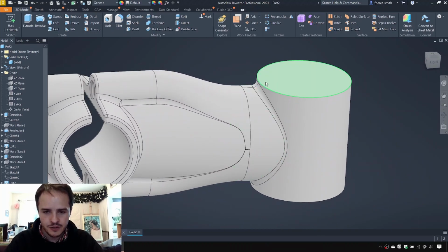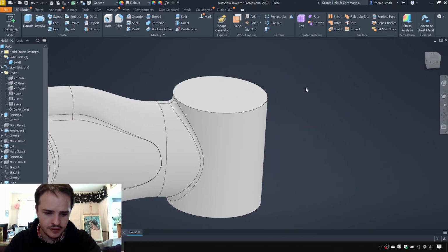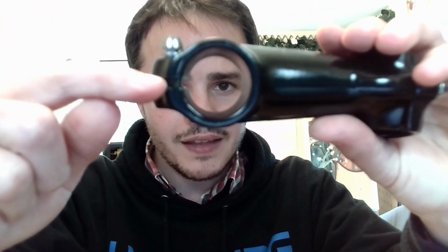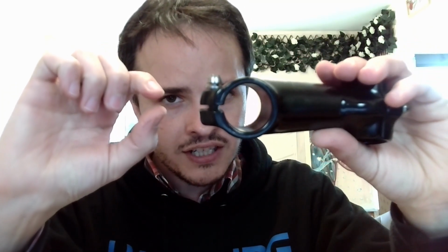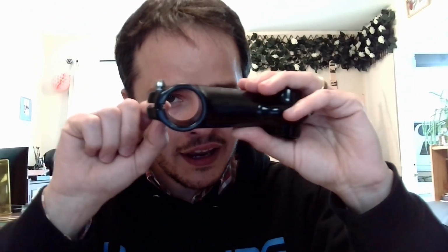Let's go ahead and do the rear shaft. So let's review our model again. We can see that it's a broken ring with a gap there. And the gap looks to be, rather than just a separation, on an angle. Now, I am going to approximate a 4-degree angle using my eagle eyes. So we are going to cut this central hole and a 4-degree wedge in there. This might not be the right way of doing it. I didn't properly reverse engineer this thing, but if you know how it's done, do let me know.